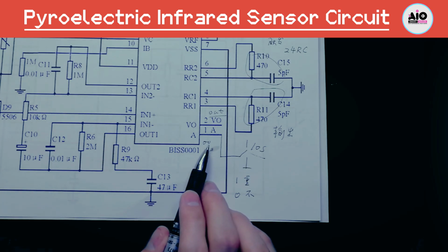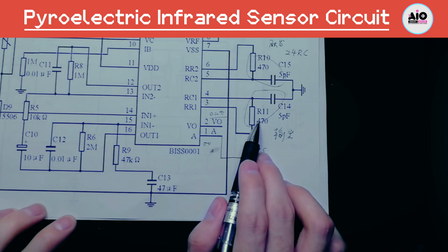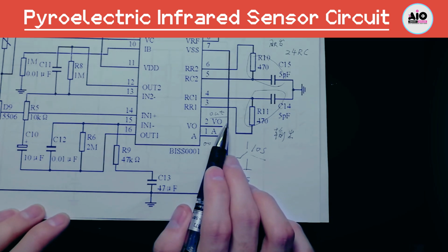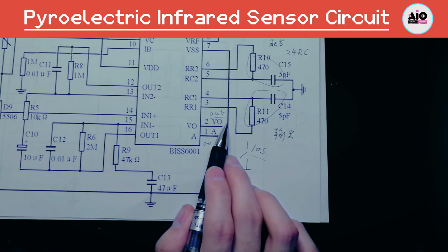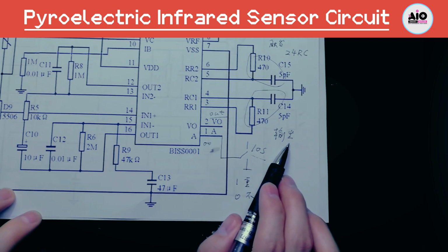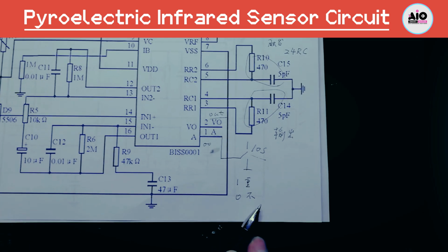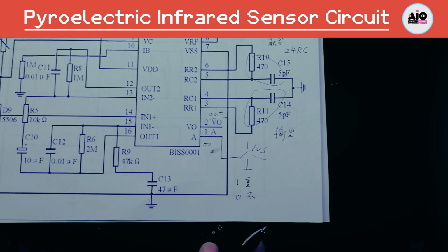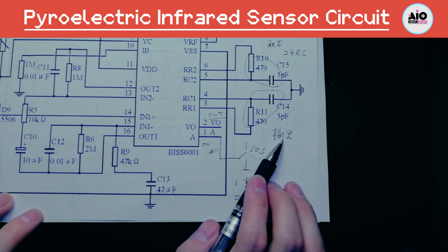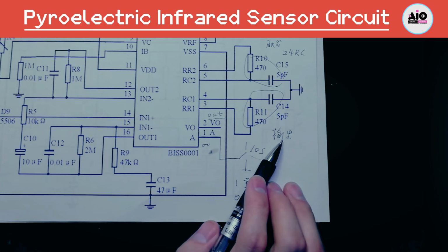What is repeated triggering? If repeated triggering is effective, when the human body moves in front of the sensor and it can always detect this effective movement, its output will always be high level. It will only switch to low level when the human body moves away and the output delay time expires. Otherwise, it cannot be triggered repeatedly.